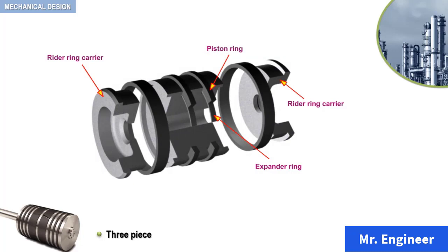The cross-sectional view highlights the presence of an expander ring as seen here. This expander ring is located below the piston rings. Its job is to make sure that the piston rings maintain a tight contact with the cylinder internals. This will be explained in detail further ahead.